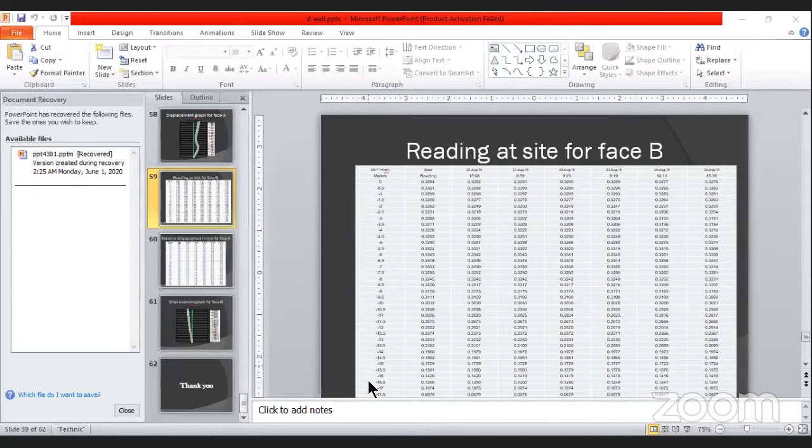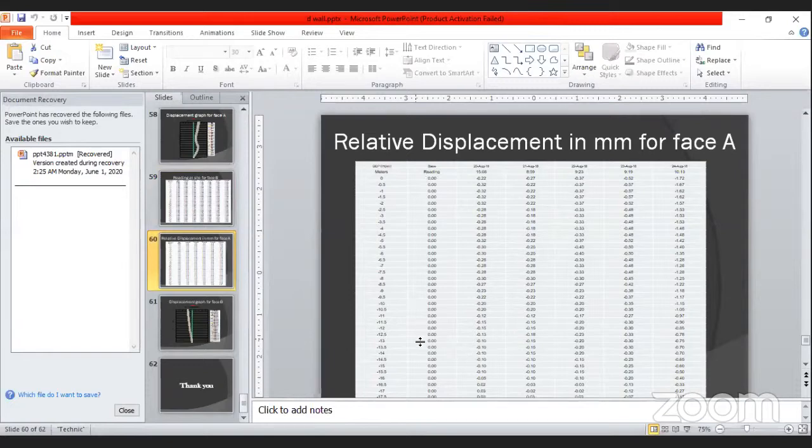Okay. So I would like to show you some bentonite setups. For that bentonite setup, we have to place 2-3 tanks, and we put it with a normal motor and pipe through into that trench, so that it will get poured continuously without any interruptions. That is a normal setup which we are using at site. If you go, you can check. It is a very easy process. Thank you so much, sir. I hope he is satisfied with the answer.